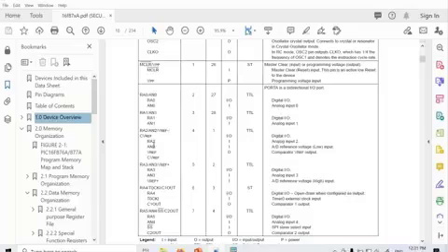For bit A2, you can see the functions start to increase up to 4 functions: digital I/O, analog input, AD reference, and comparator VREF. The strange names that you first hear, maybe we will learn later. But right now we will concentrate only on digital I/O and analog input.